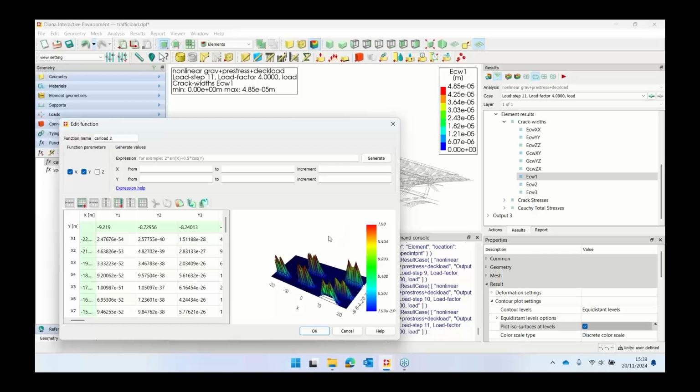With this space function, you can save a lot of effort from defining a lot of materials and a lot of loads. If you can figure out a space function that can map onto your model, then you can define a load in this way, or material. So yeah, that will be it.